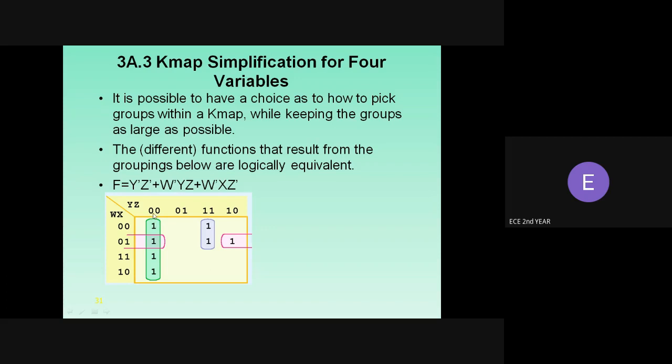First column and the last column you have to check. Here we have to see for the same variable. You see 0 for the first term, here it is 1. So y is changing from 0 to 1, and we cannot do anything with that. So the second term we have to see. Here it is 0 and here it is also 0. So the corresponding variable is z. Since both the columns are 0, we can write z bar. So the term will be w bar x z bar, right?